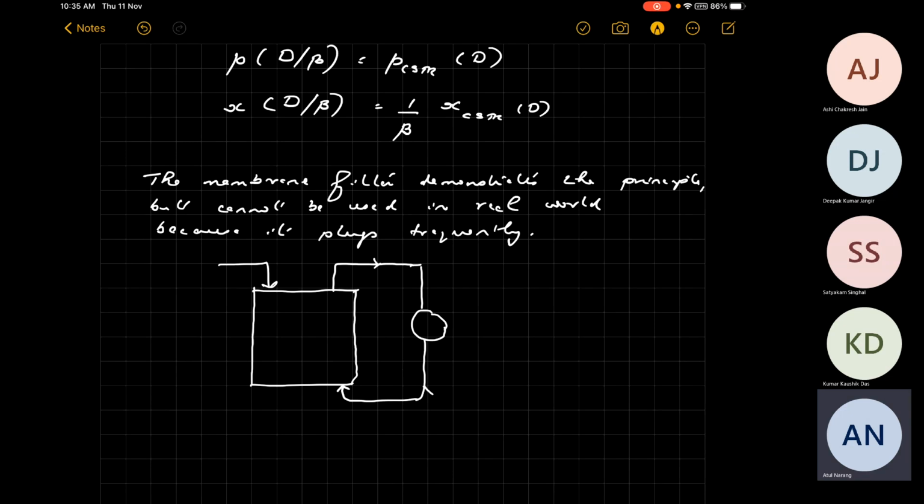And only a small part of it. So when you put it through a membrane, a thick sludge is formed. The thick sludge is recycled back. The supernatant is released over here, and most of the cells are recycled back except for a small amount. So essentially, this is your membrane.